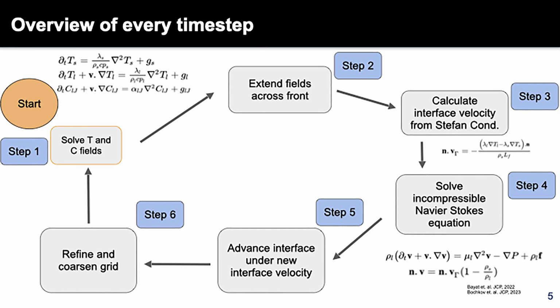So I mentioned adaptive grid. It is very necessary for a problem like this. The most interesting physics is happening very close to the interface, so you need maximum refinement there. If we had that level of refinement throughout the grid, this simulation would be too expensive to run.